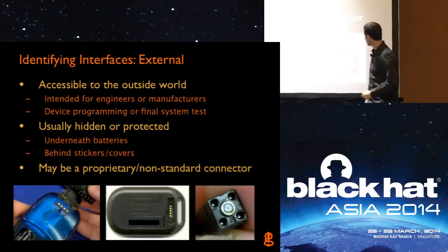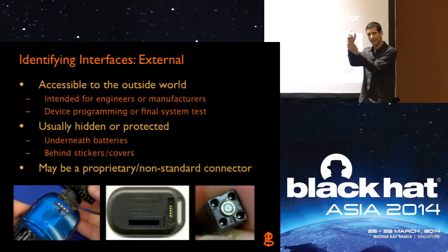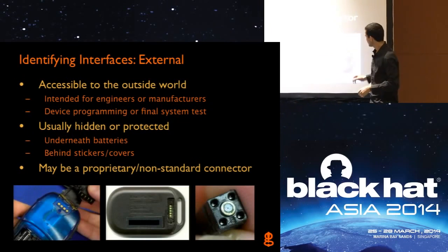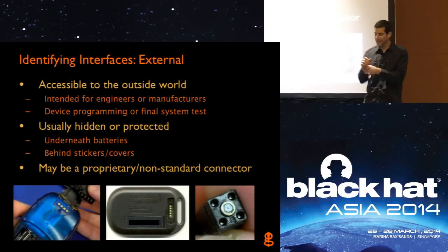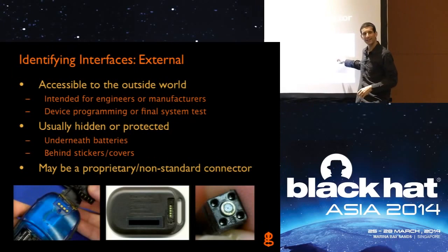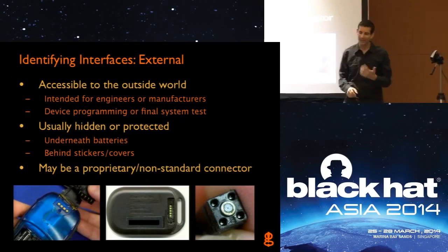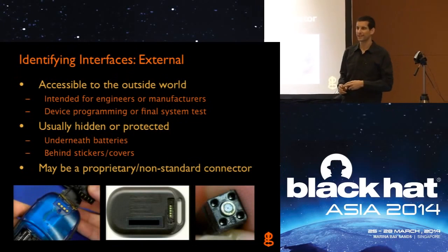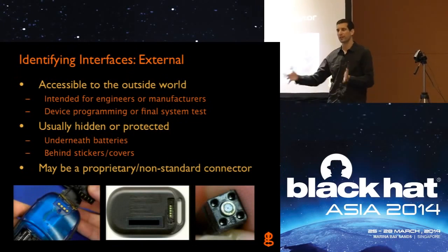It's like, okay, is that an interface that I can use, or is that a read-only interface or a write-only interface? Who knows? This one here is from a Jawbone Up wristband, the wearable wristband device, that has a little button at the end that you can select modes. And that device is pretty cool. It's like a molded rubber wristband. But if you take this cap off, here's the button. There's actually 4 other connections on there. So you go, okay, that's probably the programming interface to program the microcontroller during the production process.